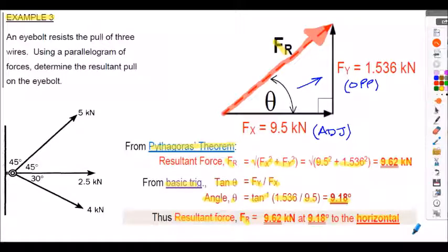I strongly encourage you to always sketch the vector diagrams without exception to make sure you get the vectors in the right direction. In example 3, the summations of Fx and Fy are positive, but in other solutions we review, they might be negative in sense. So in summary, that Fr value we've calculated, that one force at that angle, represents the entire system over here of the three forces applied. Applying the Fr is equivalent to applying those three forces simultaneously.